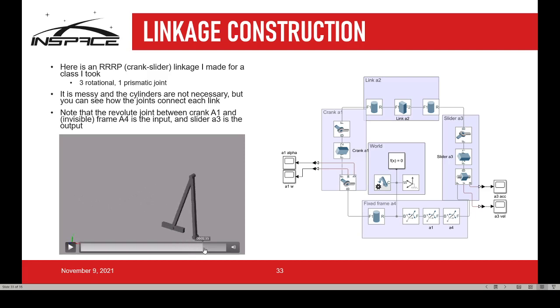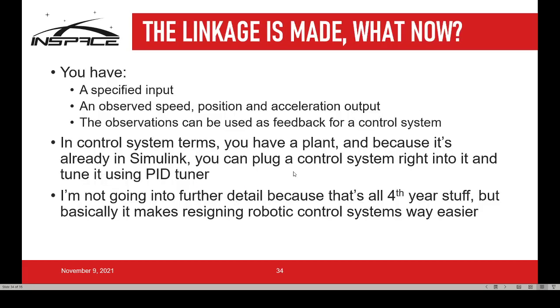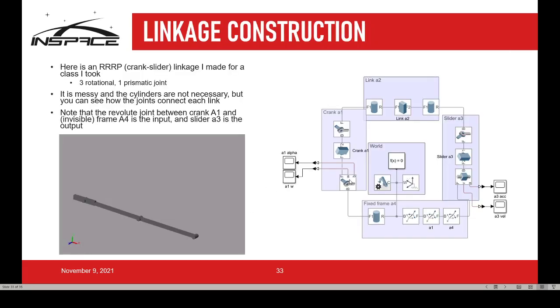But more importantly, you can specify inputs at any point, and then observe the outputs at any point. So as part of this project here, we were having to put an input at this one, watch the output at the slider. Obviously, it's going to be a pretty complicated number to know exactly how much torque you're doing here and how much force that responds to at that point over time. Well, with this, you can just look directly at it. It just generates it for you. You save a ridiculous amount of time. It's crazy. Just by setting that as your output.